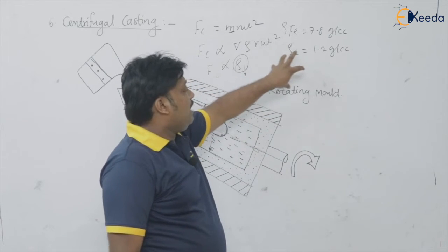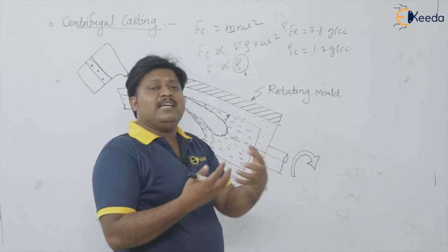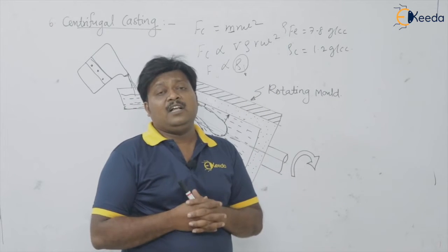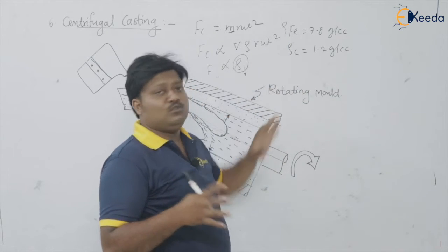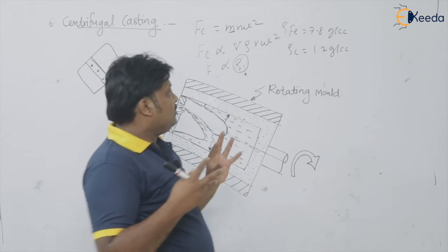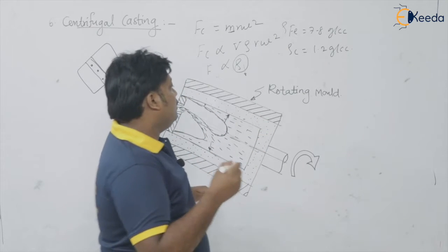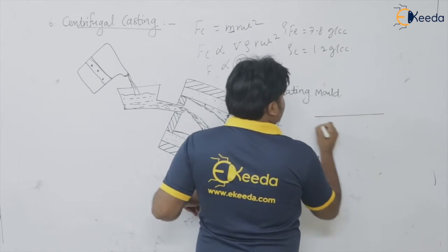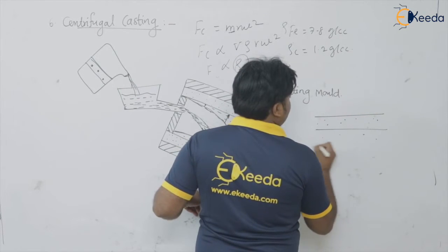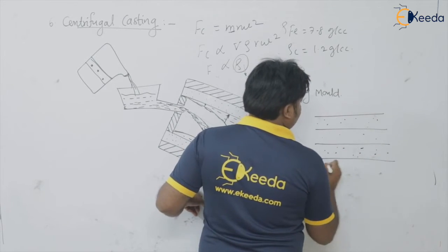Carbon and iron try to separate, but iron has a huge affinity towards carbon, so they do not simply separate. So if we look at the microstructure of such steels, we see layers rich in carbon and poor in carbon, rich in carbon and poor in carbon.